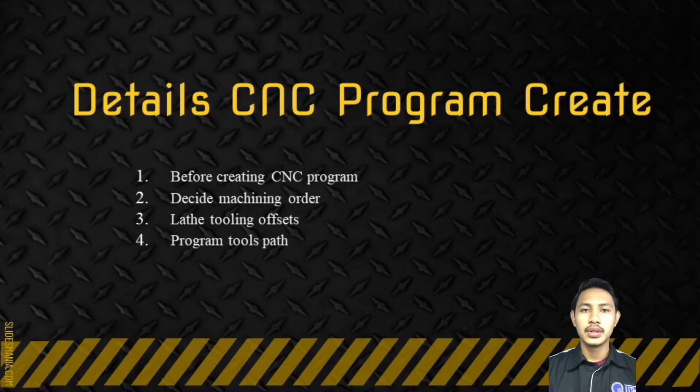For example, M03, M04, and M05 are spindle switches. G00 is rapid move. G01 is linear cutting move. G02 and G03 are arc cutting moves. And the last, M30 is end of program for the machine.